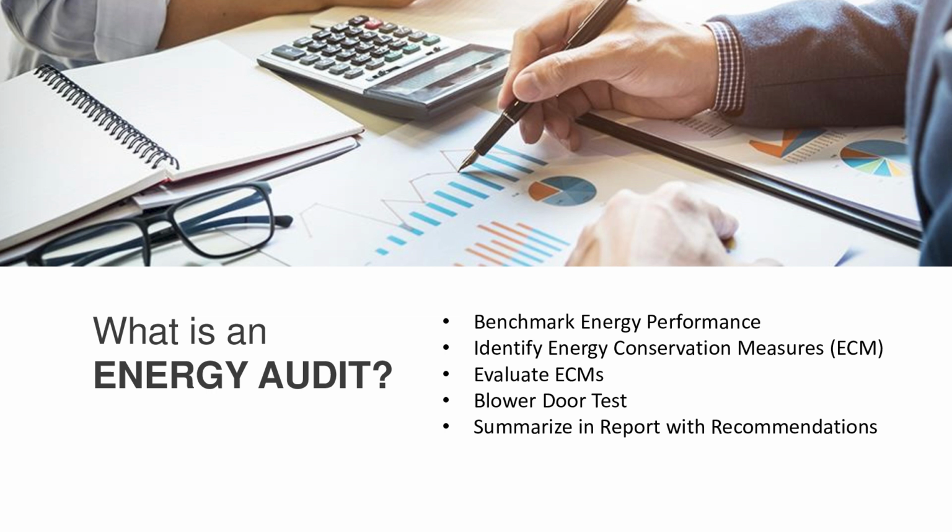And then a blower door test as well. So blower door test is something which is typically required to comply with certain programs where you're evaluating how leaky your building is. And then there's energy conservation measures which would be applicable to address any leakage in your building. And then you're summarizing that with recommendations at the end and hopefully creating a plan that could last from 1 year to all the way to 15 to 20 years. And it's all with respect to where you're at with your home, what your plans are with that building or whatnot.